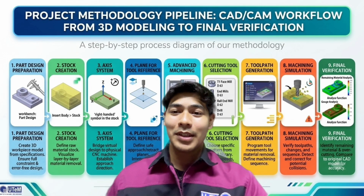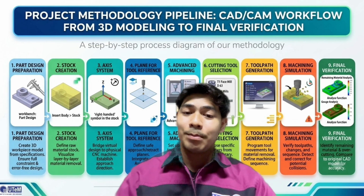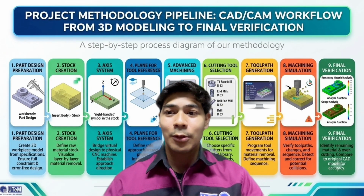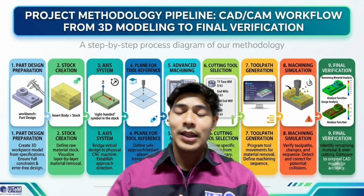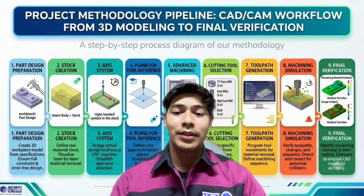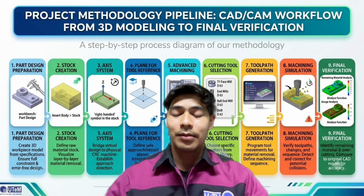So in this section, I will explain the methodology used to complete our CAD-CAM project using CATIA software. So the first step, as we can see, part design preparation. First, we create a 3D model of the workpiece using the CATIA part design workbench. Every feature, including the pocket, hole, curved surface, and dimension, was designed according to the engineering drawing provided. After completing the model, we checked that all features were fully constrained and free from design error before moving to the machining stage.